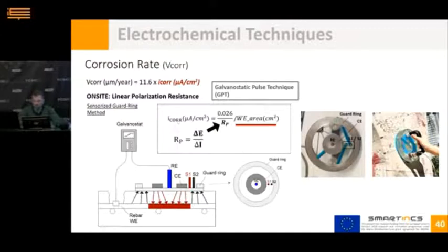To ensure that confinement is correctly performed to the desired area, the most advanced techniques or devices use two additional sensors or electrodes, S1 and S2, in charge of controlling at all times the current to be applied by the guard ring so that the confinement is correctly performed. It has been shown that if the confinement is not controlled by these two sensors, the results obtained are normally erroneous.